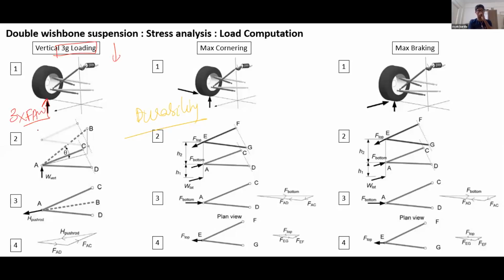Before you put your cars onto the field, you would probably measure the load coming onto each corner, right? So that would be the FAW by 2 for that corner. So 3 times that force is the assumed value or the maximum value that can come onto your suspension, all right?